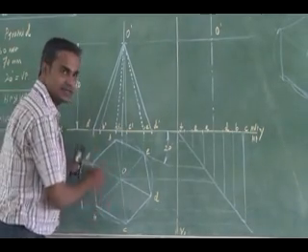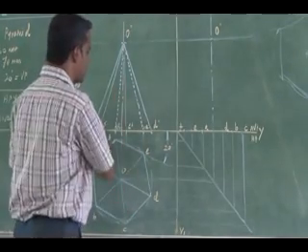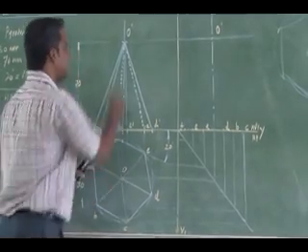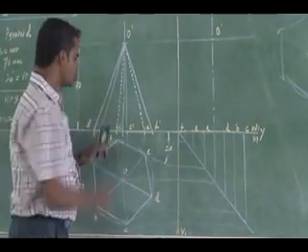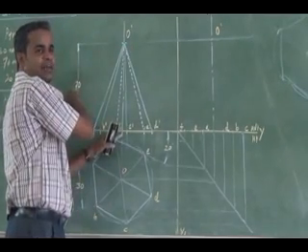Then you mark the apex, and draw the slant edges in the top view. Then you project these base points in the front view. First of all, you project the apex and show the axis line. Then measure the height, 70 mm. Right?